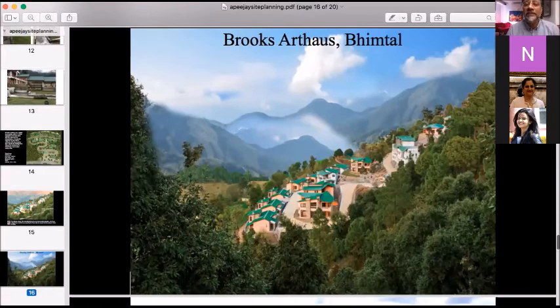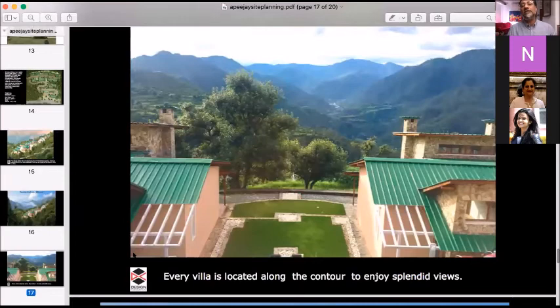And because of this, the slope of the roads have been created in such a way that the water drains off towards the two canals. We had a challenge about how to drain the water which is within each plot or site. Now, this is a view from one end looking towards the valley. And you can see even in the landscaping below, there are three terraces defined by retaining walls.